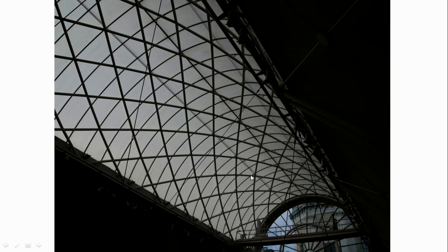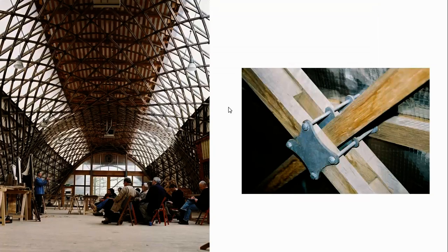And remember, we talked about the offset. So this is the roof at the Imperial War Museum in South London. So here we've offset the structure. Don't ignore these, because that's just the glazing curves. But the main structure is this sort of grid, a series of arches, but they've been offset against each other, so that you get a very efficient, stiff roof structure. Here's the same thing happening again. I talk about this a little bit more when we look at timber frames, timber structures next term, but again, it's the same principle in operation. You may have heard the term grid shell applied to these kind of structures. G-R-I-D, grid shell structure. So that's a grid shell, that's a grid shell.